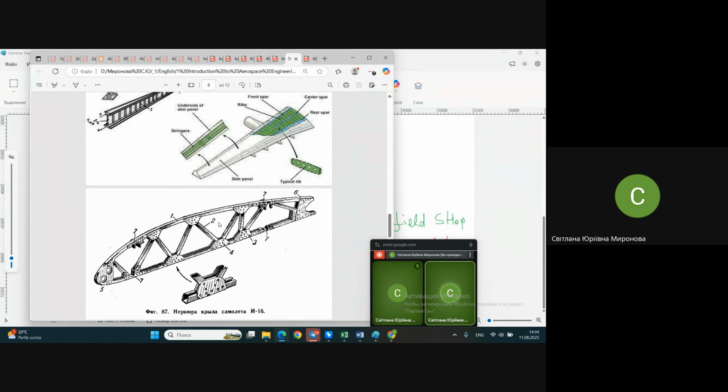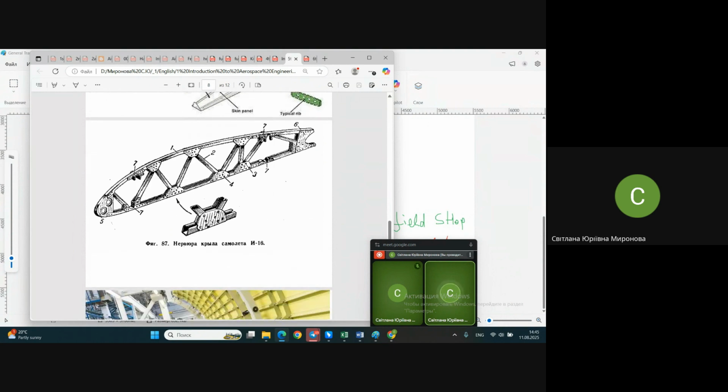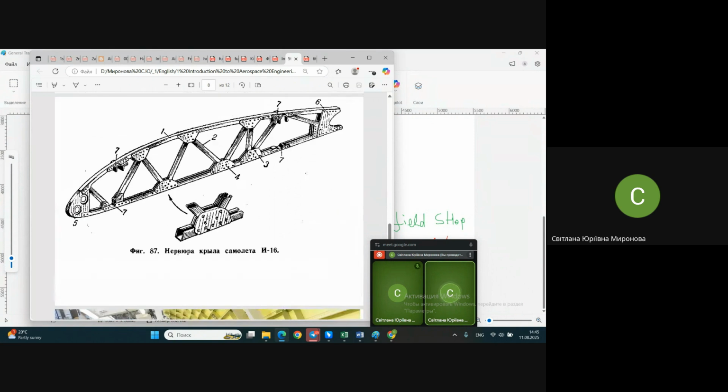We mostly use rivets for metal airplanes, for modern structures of, let's say, middle class: passenger airplane, cargo airplane, military airplane, business jet. Mostly they use riveted joints, including screws and bolts. Not much. Bolts only in heavily loaded places usually. Mostly rivets. Some materials are joined by welding, for instance. But welding is a rather specific process, and not all elements of the airplane may be joined by welding because of the peculiarity of the process and reduced strength and so on.